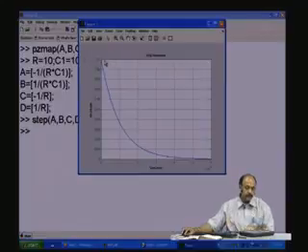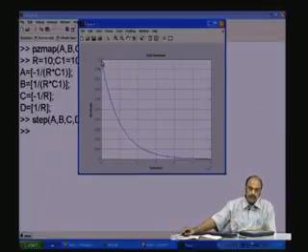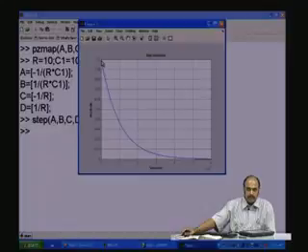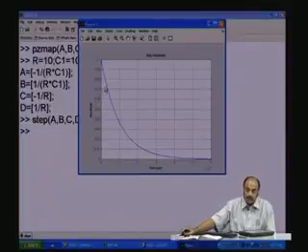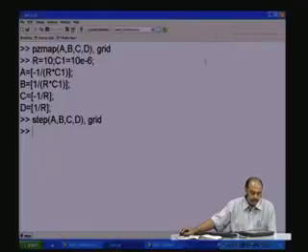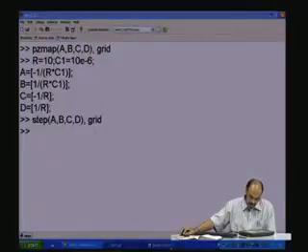So, you see the current, initially there is a high current because there is a step which is a high frequency, capacitor acts as a short, V by R. Initially there is no voltage across C, the whole voltage appears across R. So, 1 divided by 10 ohms, 0.1 amps, and that starts exponentially decaying to 0 as the capacitor charges to full voltage. This is the nature of the current waveform through. So, as I was saying, you can see whatever output you want to see.